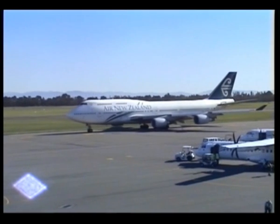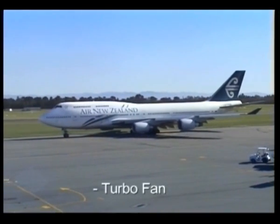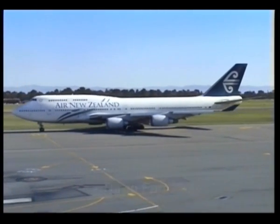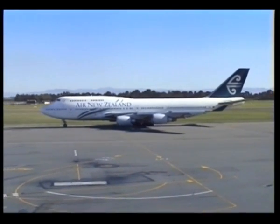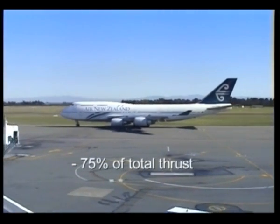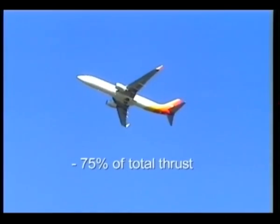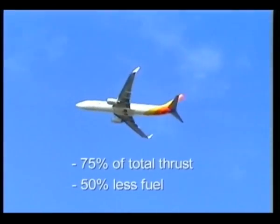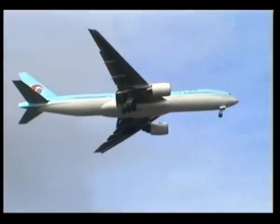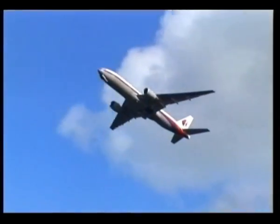The turbofan engine, which is similar to the turbojet engine but employs extra turbine stages to drive a fan. The fan accelerates air around the outside of the core engine and produces typically 75% of the total thrust. For equal thrust, the turbofan engine uses around 50% less fuel than the turbojet and is much quieter because its exhaust velocity is slowed down by the mixing of the exhaust gas and the cold air from the fan.